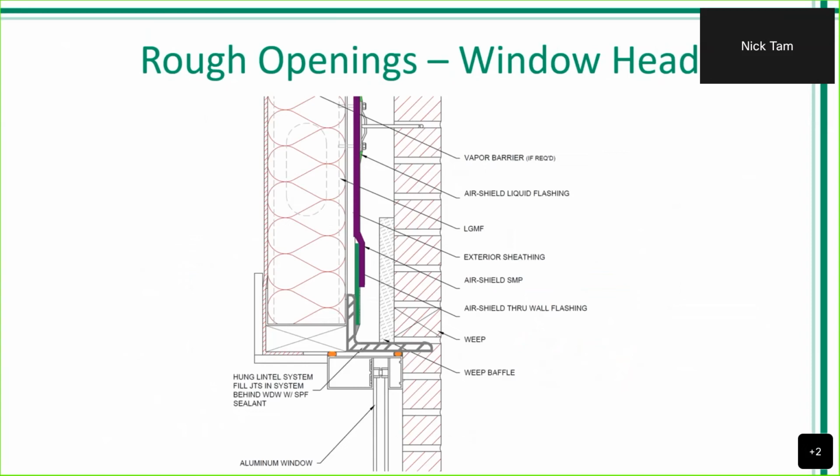Also, for the metal lintel that I mentioned earlier, pretty much just reiterating what I said earlier. In a lot of cases, we'll still encapsulate the head there, but in this situation, we're showing a piece of peel and stick transitioning on the lintel, finished off with the primary membrane shingling on the top.